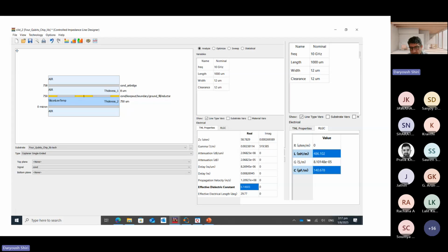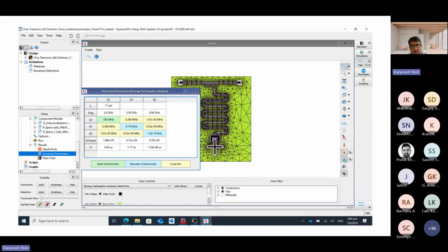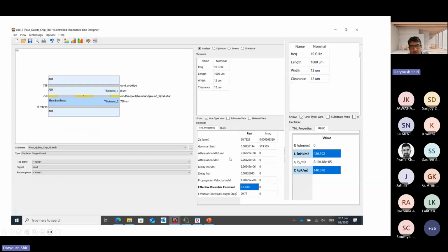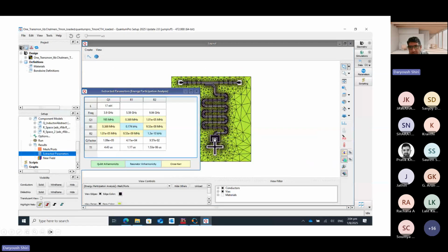Initially, it's better to just start from this. Instead of jumping into a big chip, just design a single chip, characterize it, sweep these parameters, for example, the length of the resonator, or the claw shape, or length, or gap, and things like that, and have a bunch of plots and fit equations for yourself as a designer.